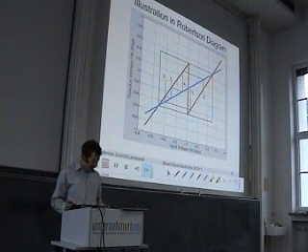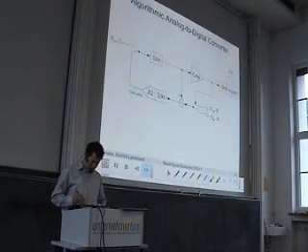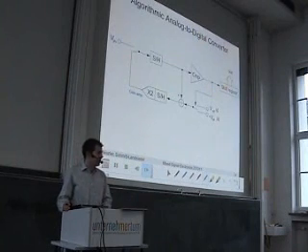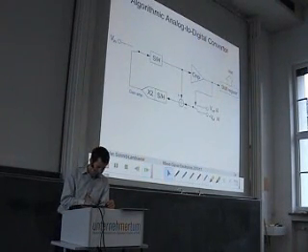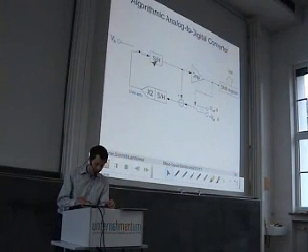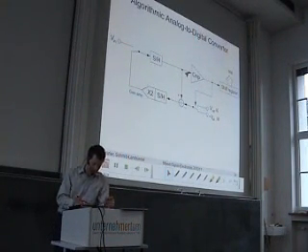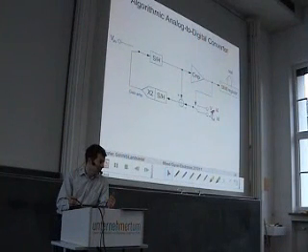Okay, finally we can place this in a block diagram and look at the components that we have here. We have our input voltage that is sampled by a sample and hold. The sample and hold version of this voltage is then compared, and depending on the sign we either add or subtract Vref over 4.